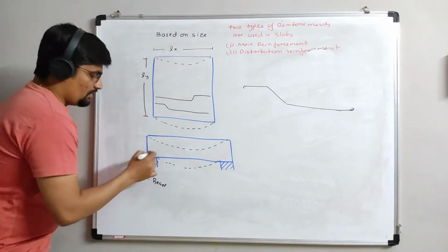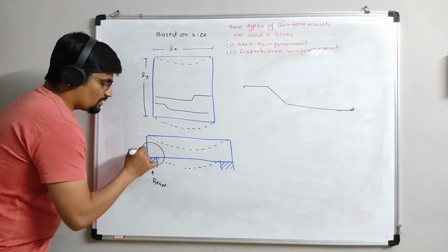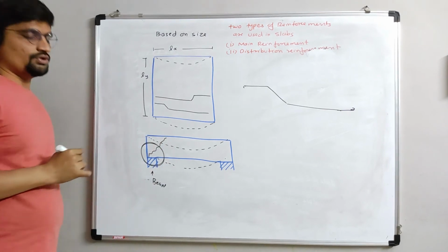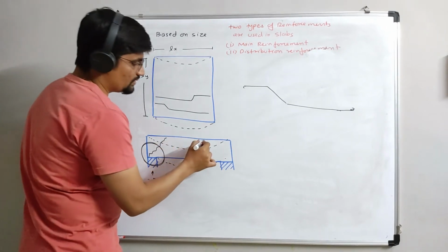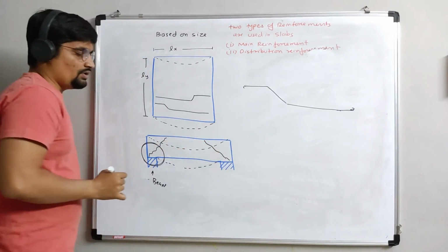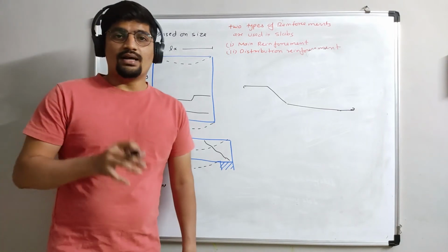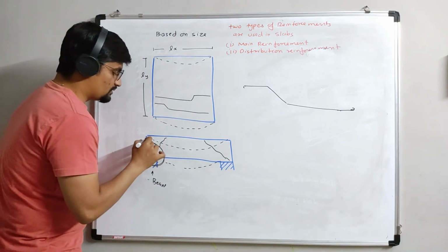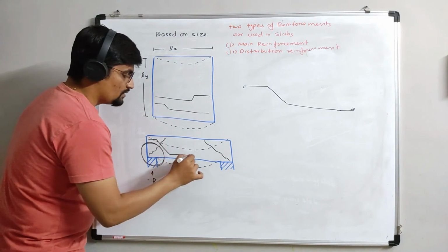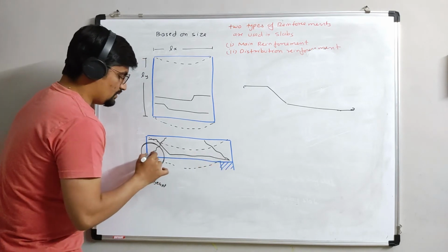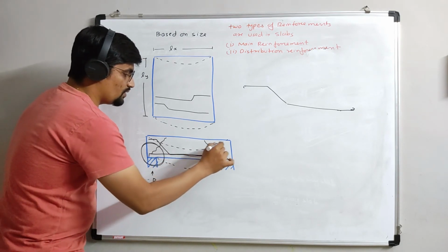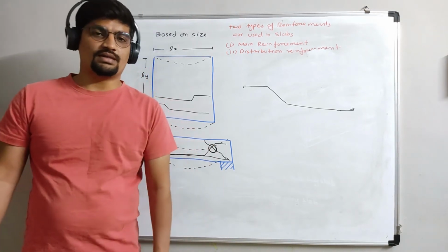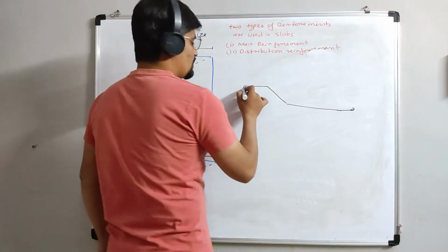So here at the support condition, shear failure occurs at 45 degrees due to tension, due to fixity. So to prevent that cracking, we provide the bent up bar at 45 degrees at this stage, like this. It resists this crack, which resists the failure of the slab. Okay, that's why we use bent up bars.